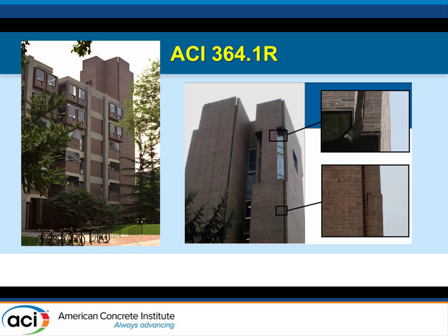So I said before about concrete creep and shortening. The towers on this are only 100 feet tall. So normally you wouldn't think there'd be a lot of issues with shortening of that 100-foot concrete stack. Unfortunately, you also had 100-foot tall brick masonry that went straight up the building. It had relief angles in it. Unfortunately, when they built it, they really didn't provide any gaps between the relief angles in the brick.